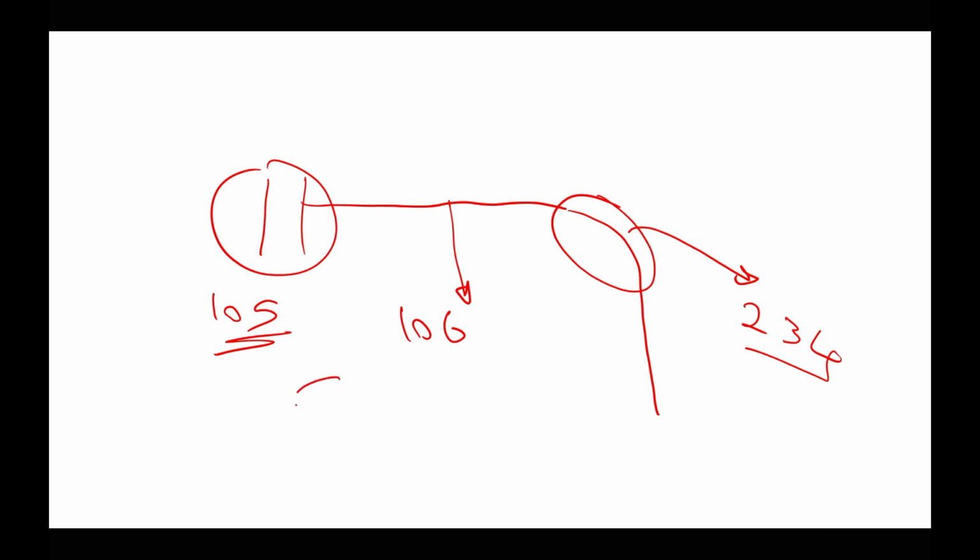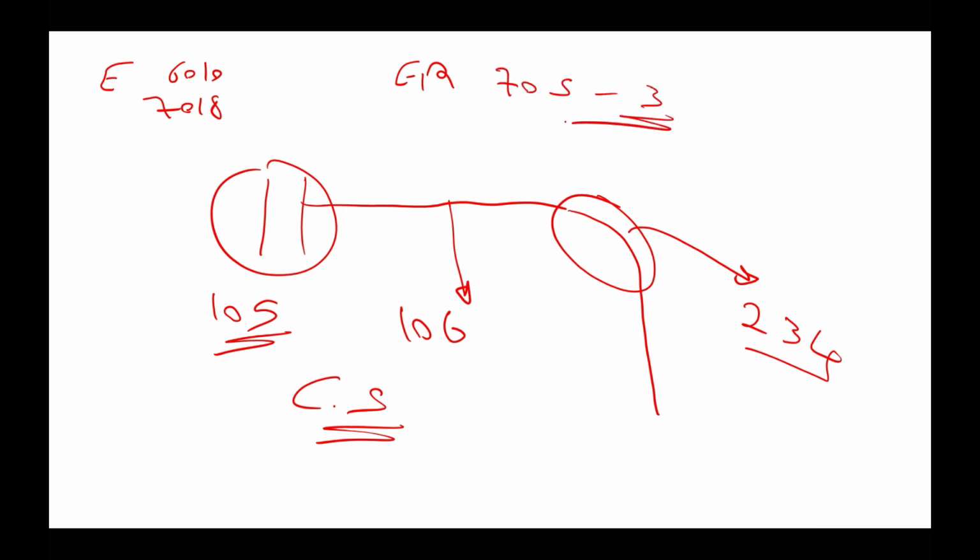All of those are carbon steel materials. To weld those materials, I will use, for example, electrode 6010 or 7018 if it's electric welding, or if it's argon welding, I will use ER70S-3. All of those are carbon steel materials having the same weldability and the same P number.